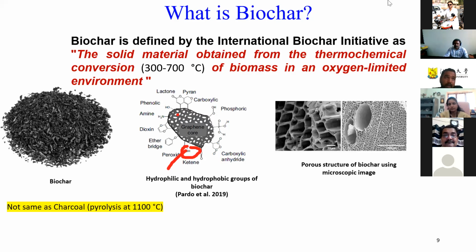No, there are a lot of studies on biochar and heavy metal absorption, especially in wastewater treatment. Too many studies are there. Even in soil cases, there are. But the problem is they are mostly laboratory studies, and the major problem is if you want to use it in the field, you can use it to reduce contamination in the soil in some form. But the problem is the long-term usage. When you mix biochar in the field, how will you maintain it for the long term so that it keeps on reducing the contamination? That is one problem. Also, once the biochar takes the metal to its surface, its extraction may not be very easy if you want to reuse it again. So that is one problem.